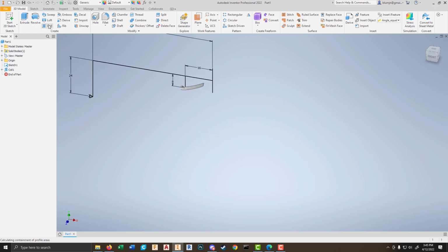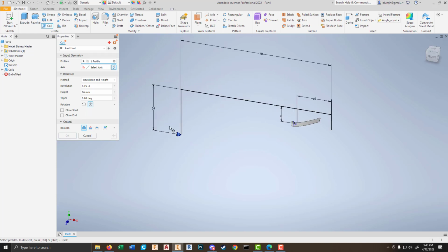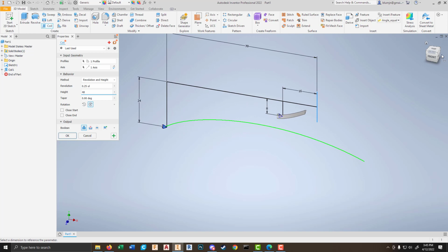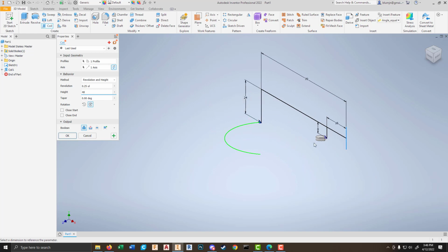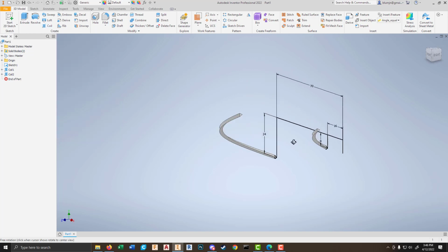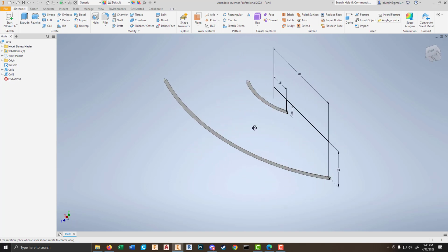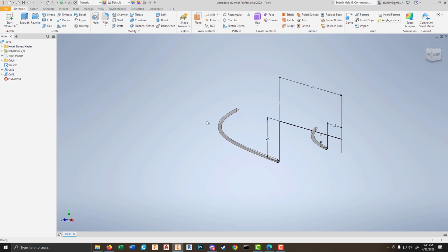So we're going to do the same thing. Same exact process. I'm going to zoom through it a little bit more. Grab this guy, grab the axis. It's going the wrong way again. And this time we want to go 48 millimeters. And I'm getting these numbers. Double check. It's unflipped itself again. There we go. I'm getting these numbers by doubling my offsets, right? I want this line to be sort of on the horizontal midplane. And we want this to be a new solid. All right. So now we have these two guys. And you'll notice they do not look a lot like a propeller. Don't worry, they will. So we're going to leave this sketch in the background as sort of a thing that we can deal with.